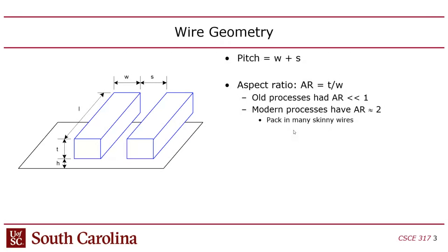However, if you're modeling the delay of longer, bigger wires that go off chip, that would connect the chip to other chips, or connect boards in a network, the inductance there is much more significant, so they'll model long wires with RLC as opposed to just R and C. But we won't worry about that in this lecture.